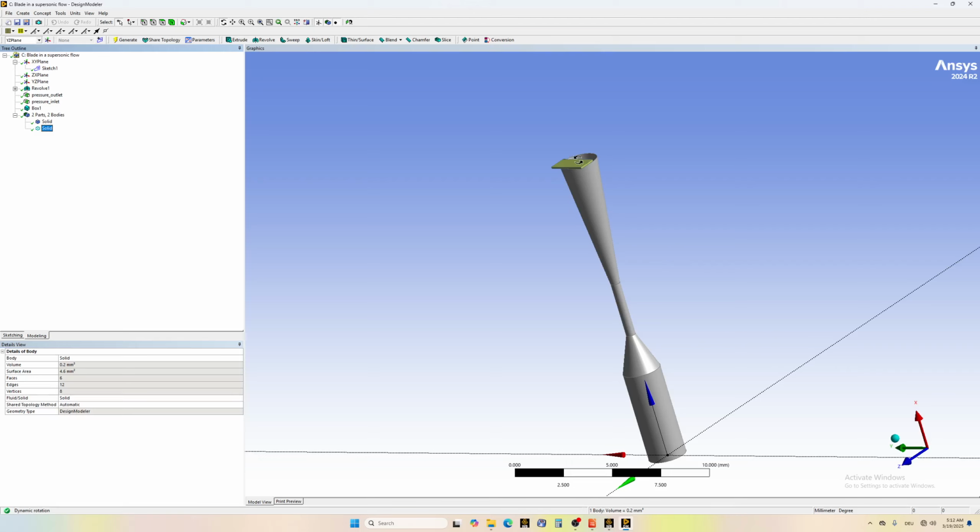So it will try to mesh the interior, and if this body is extremely small, you'll need a very small mesh, and it will be more and more difficult to mesh it. To avoid any problems, since anyway we don't care about the thermal properties of this body, there is no heat transfer between the gas and this plate. So it's considered adiabatic like the rest of the wall, the nozzle wall.